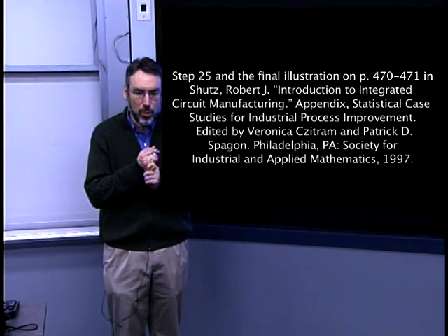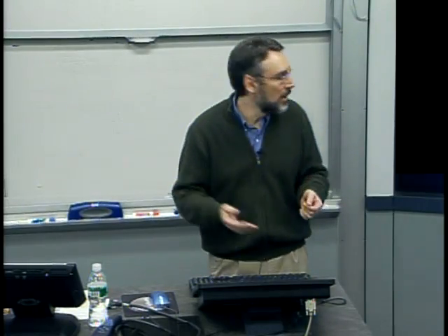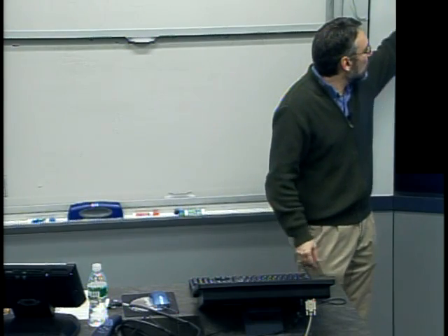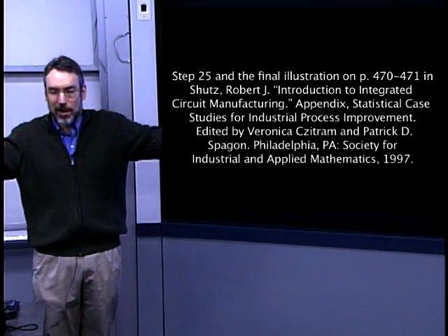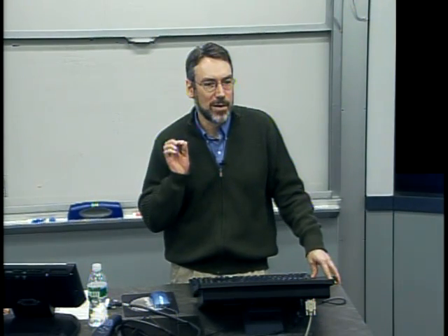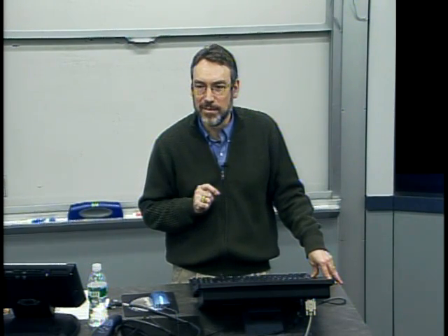One of the most important things that you have for control of this lateral differentiation is photolithography. Notice we were never just depositing aluminum directly where we wanted it. It's always a deposit everywhere, because you can do that in parallel across the whole surface of the wafer, and then have to go back and do a subtractive process to typically remove what you want. There are very, very few steps where you can selectively grow or selectively add material only where you want it. Okay, so that's an example of a huge constraint in semiconductor processing.